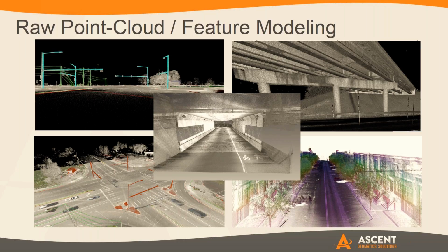Yeah, the nice thing about the raw point cloud is there's programs we use that you can run through, especially on, let's think about highway projects where you're trying to figure out what are bridge heights. You might not care about anything else within that point cloud, but the height of the bridge, where's that deck at, where's the lowest point at the beam, you can just automate through, and we can pick out those heights that way they can understand what the heights are as you go through.